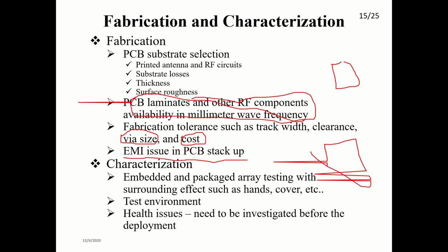Testing is okay, we can do this, but creating a test environment is another challenge, because you need to have millimeter wave absorbers ready, and you need to decide how to deploy, what sort of design for a scatter chamber to use. How best can you do the reflector design, feed horn design, and positioner resolution, and how are you going to integrate with the several antennas? You might have seen an OTA measurement chamber. So proposing and analyzing this method is also a good opportunity for everyone. If you have a very good understanding of how this setup works, that also gives you plenty of opportunities.